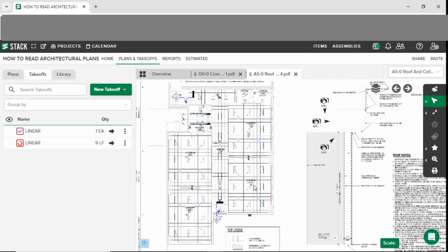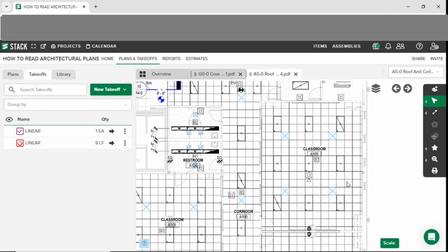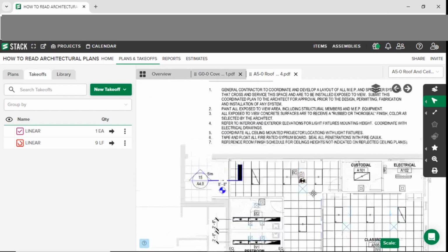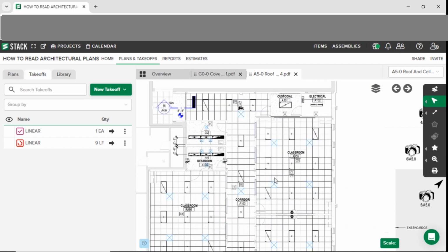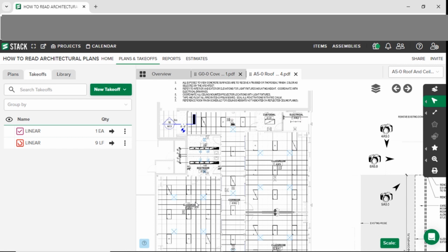You'll be able to find heights, materials, things like notes. So here you have notes that pertain to this ceiling plan. You'll find where the lights are gonna sit, but you won't find diagrams and things like that of electric or wiring. That'll be on the electrical plans. You'll find some things maybe on some ceiling plans, but you're probably not going to be able to find everything. That'll be another sheet and another set of plans, not in the architectural section.